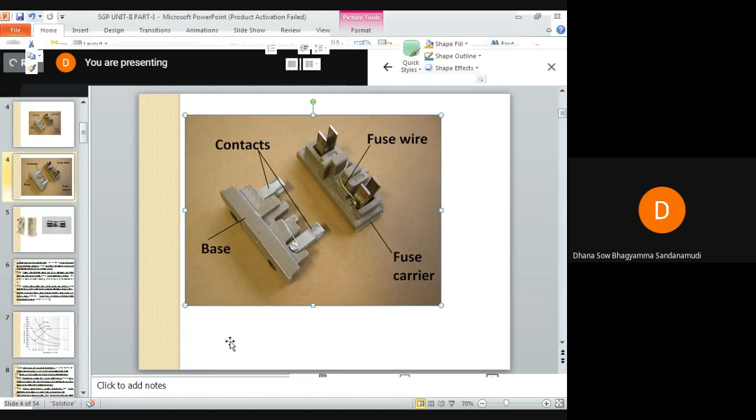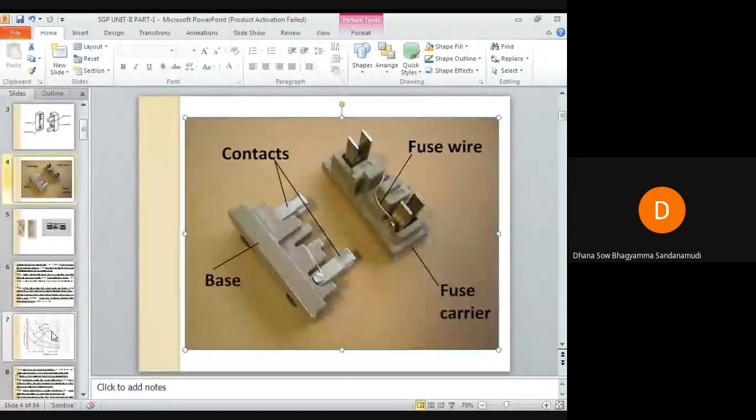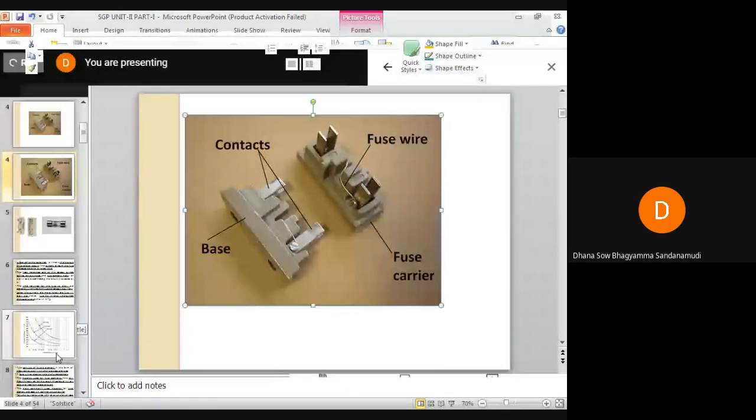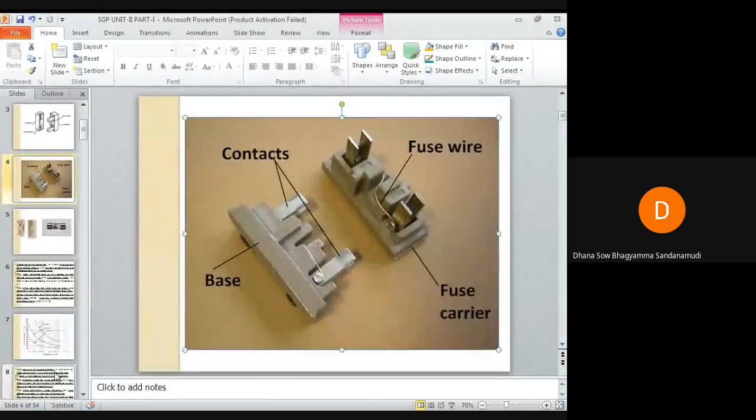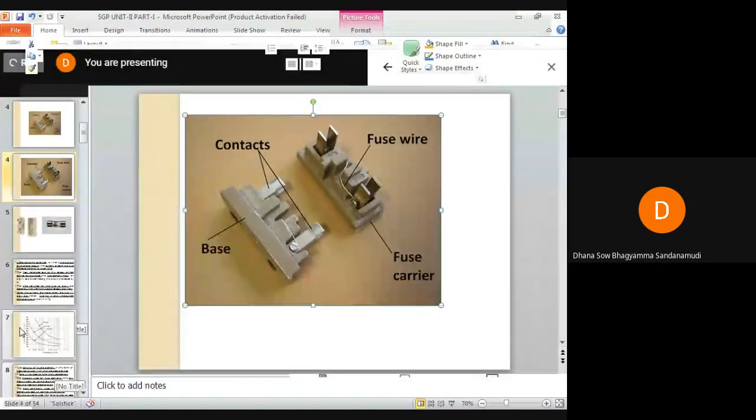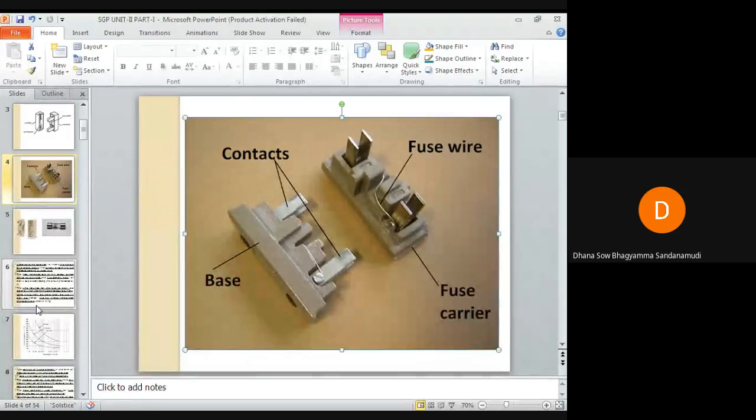It won't blow out quickly. That's the reason zinc is used as a fusing element in cases where we don't want the fuse to blow out very quickly. Compared to other materials, the time taken for the fuse to melt when the fusing element is made of zinc is very long.